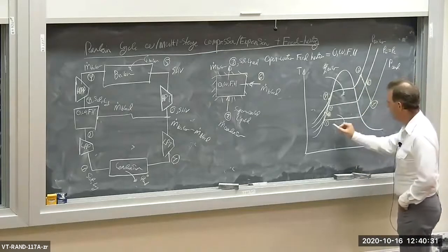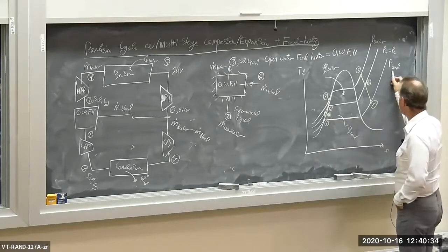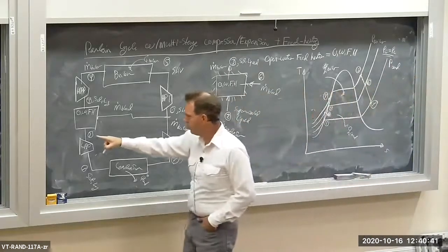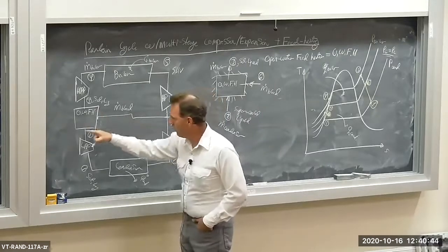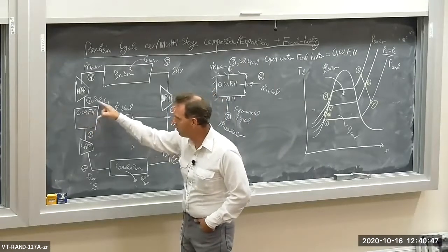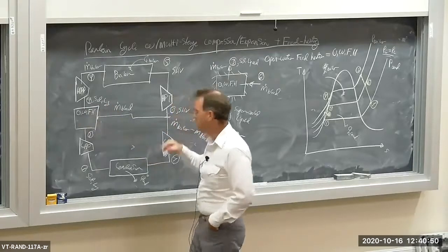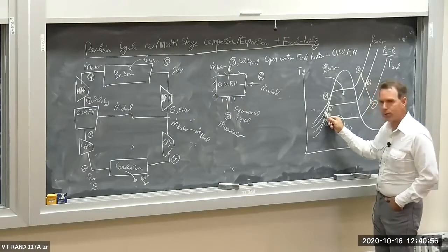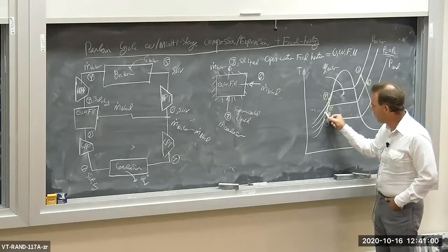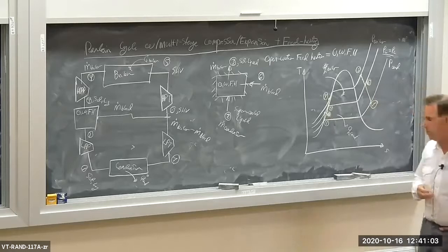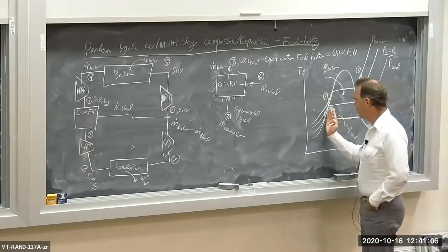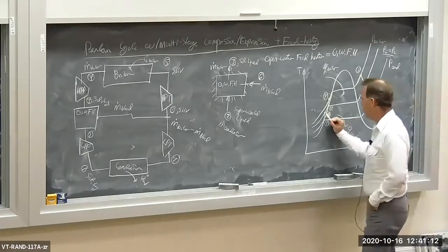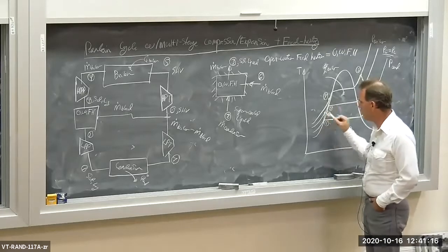So here's your condenser pressure. Here's your P1 isobar, which is your condenser pressure. We have an intermediate state pressure, which is P2 and P6, by the way. We have mixing, if you like, isobaric mixing in this feed heater. So P2 and P6 are the same. So we have compression up to the intermediate pressure at state two. Now, that is going to be some kind of a supercooled liquid. The higher the efficiency of the low pressure pump, the more supercooled this liquid is going to be. So state two is not on the dome, it's away from the dome in the supercooled liquid region.